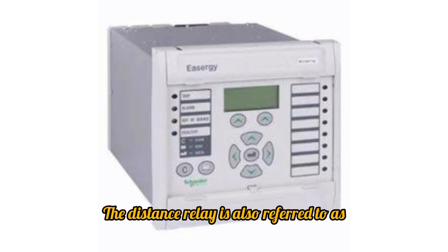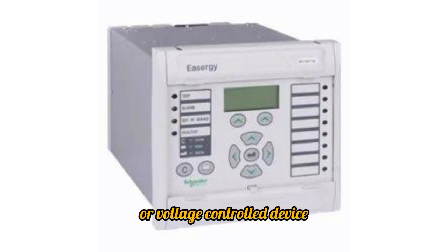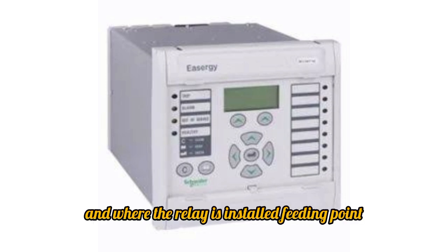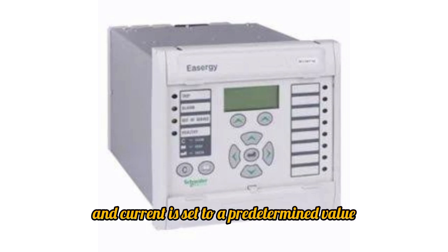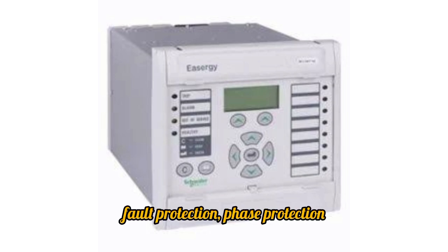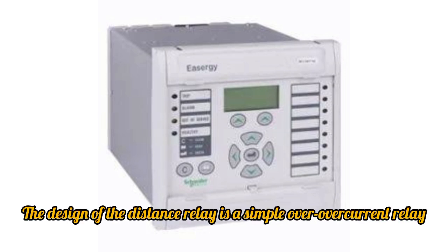The distance relay is also referred to as the impedance relay, distance protection element, or voltage-controlled device. Its working mainly depends on the distance between the impedances of the point where the fault occurs and where the relay is installed, the feeding point. The relay operates when the ratio of voltage and current is set to a predetermined value or less than the relay. This type of relay is used for backup protection, fault protection, phase protection, and main protection of transmission and distribution lines. The design of the distance relay is a simple over-current relay.